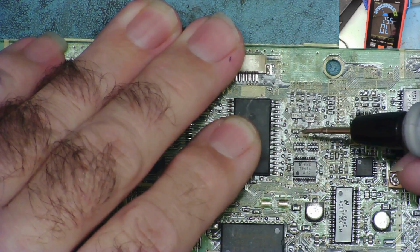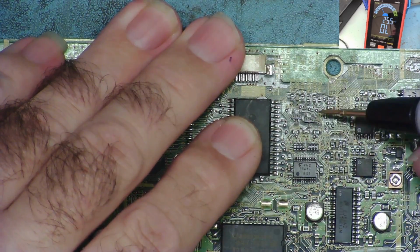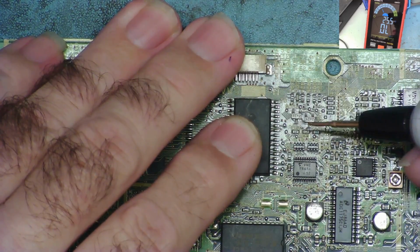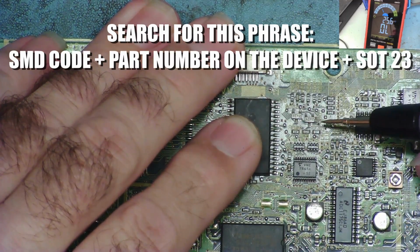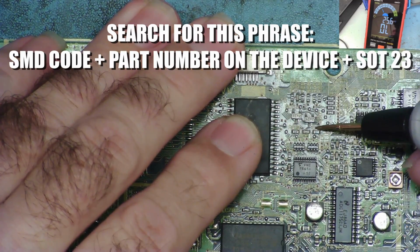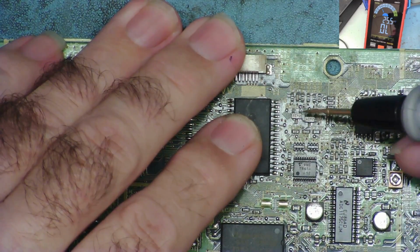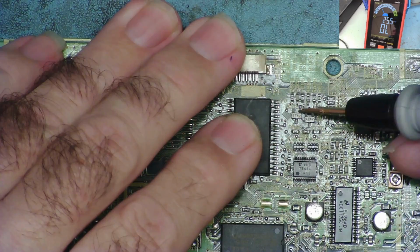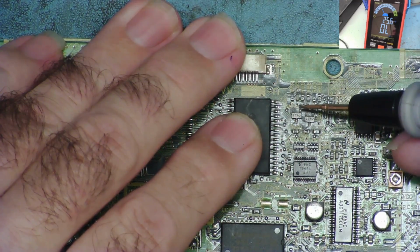This is not a part number, it's an SMD code. The easiest way to find, if you are going to find them, is obviously to use Google. And if you search for SMD code and then the size of the package, SOT-23, yeah? If you search for that, you'll probably find what they are. And it might be only the first couple of numbers in this SMD code that are the part number. The other two are possibly a date code.